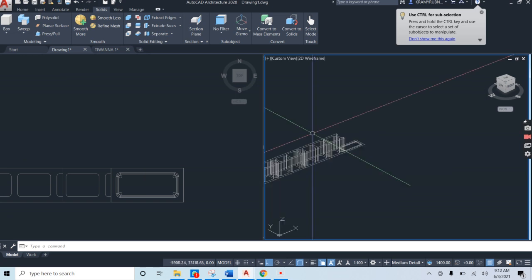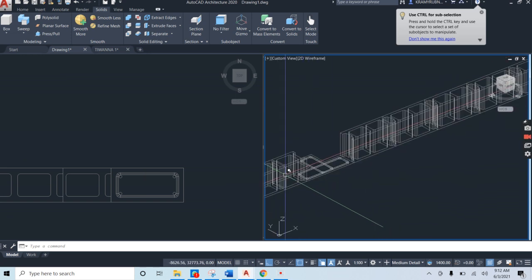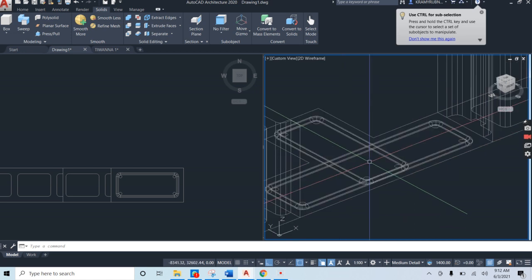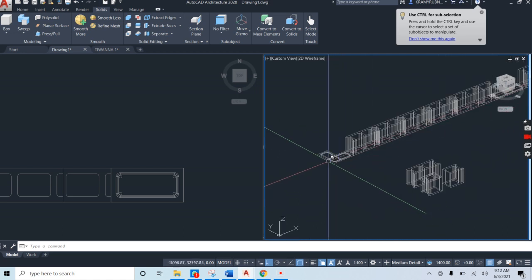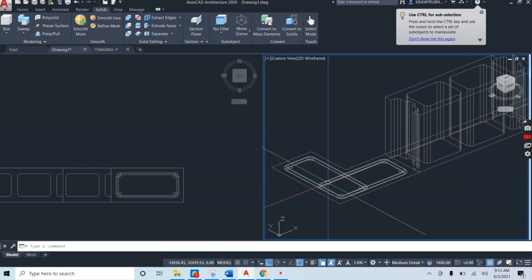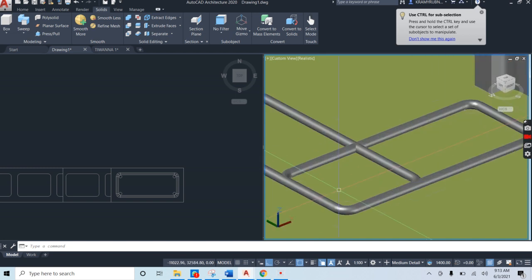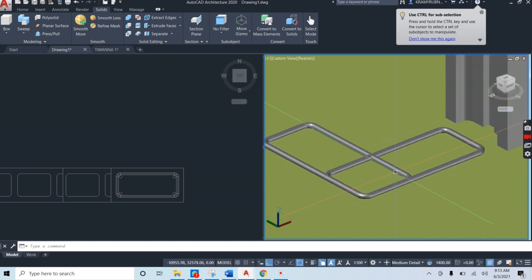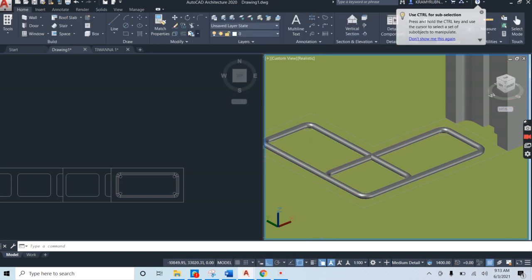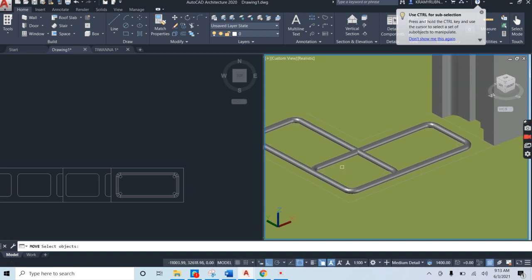But here is the thing. If we were to take a closer look at, for example, our T and our L stirrups or links, here's what you're going to be noticing. You're going to be noticing that those stirrups pretty much run through each other. What is now necessary is for us to lift a stirrup, whether perhaps this one or this one, whichever one we wish to lift, such that one will sit on top of the other.